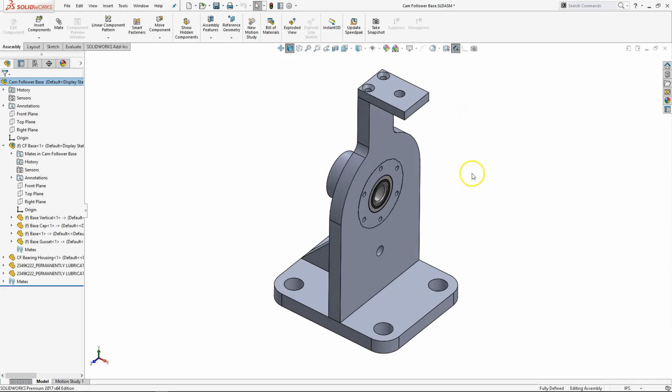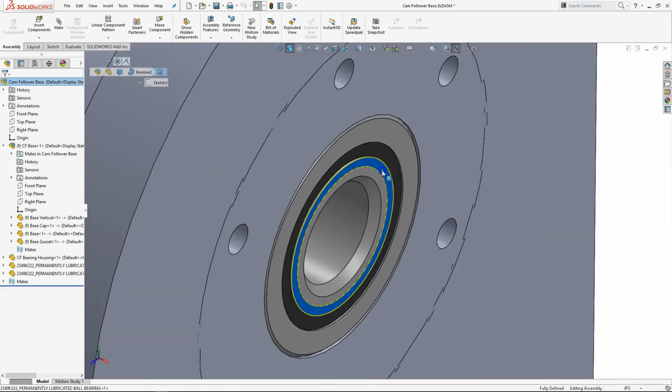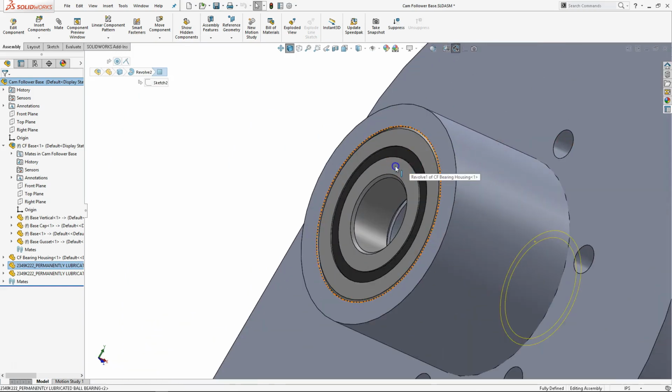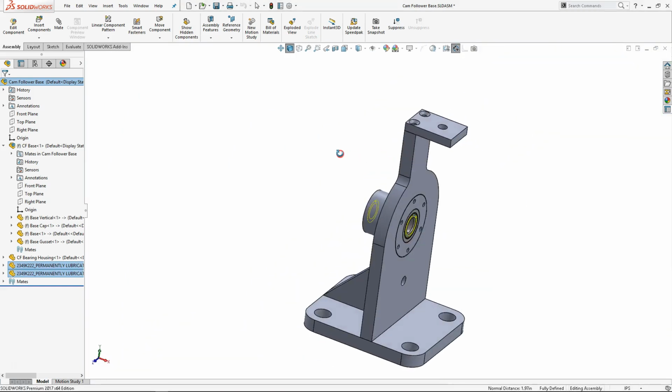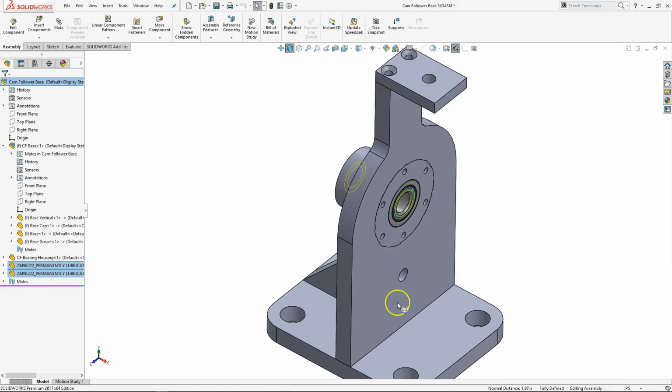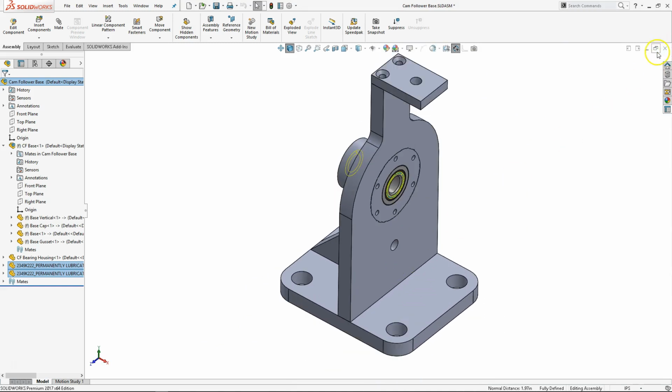So what I'm looking for is this to be a subassembly as a complete unit drawing package, and then the cam, the shaft, any of the retaining geometry would be in that other subassembly. And then of course the cam follower itself, the roller up top, would be a separate subassembly. All right, so if I come in and pick the bearing face, we jump back into inches, but 1.97 should put us at 50 millimeters.